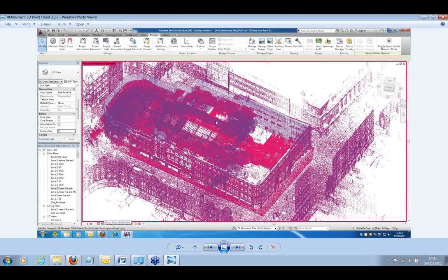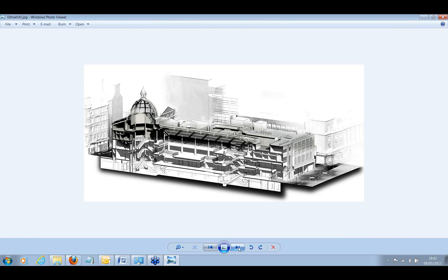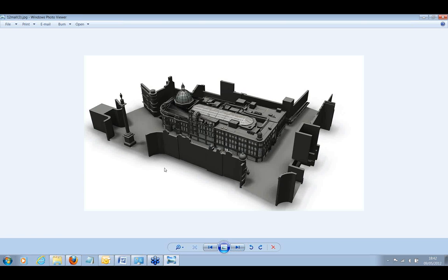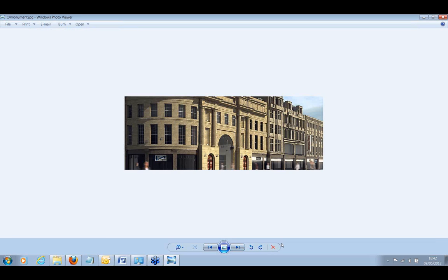One of the things that really assisted us with the modeling is we use a TrueView application, and we have that as a background reference to allow us to really visualize what we're modeling. If anyone's not familiar with TrueView, it provides you a 360-degree image from every scanner location. So we use that as a reference to assist with the modeling. And as you can see, it's in just one mass color. So it's a time-consuming and tricky process, and can potentially be error-prone without using something like TrueView to reference from. But you can still get good results, put the time in, and it gives you an idea of what we finally built up from it. Wow, that is fantastic, to build a full model. It's amazing the advances that scanning technology has made over the years.